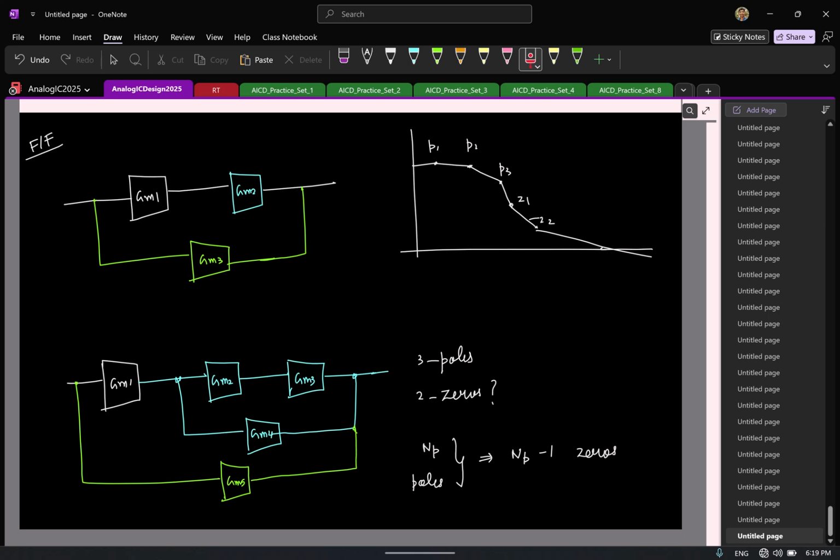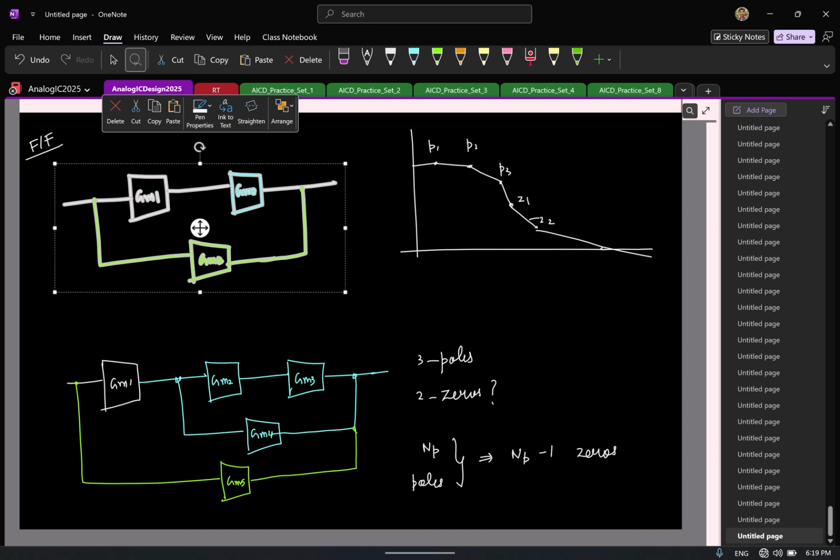That is the way you can extend it further. Now again, it is not necessary that, when we came to the 3-stage feed forward OTA, we replaced the second stage by another 2-stage feed forward OTA. But is there some other 2-stage OTA that I know? Miller. So basically you can replace the second stage here by a 2-stage Miller OTA also. That's also fine. So that gives rise to more combinations.